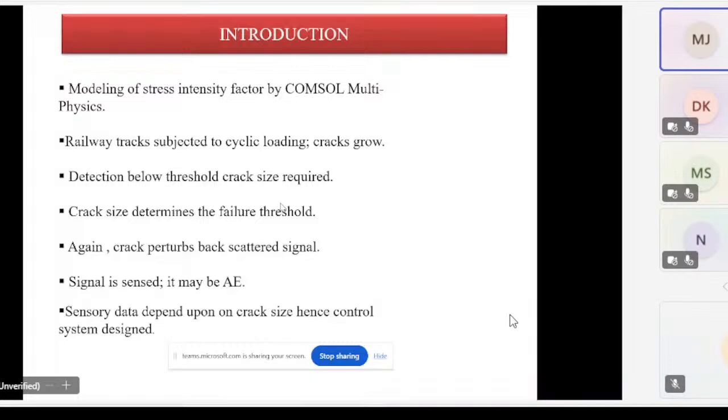If you can calibrate these things, then you can calibrate the deflection against the reduction in the acoustic emission count. This is the technique which people are using for detection of the growth of any irregularities.